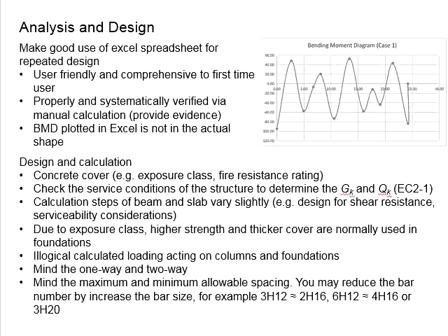And also you need to beware of illogical calculations of the loading acting on the columns and foundations. Sometimes, because you did not actually do proper verifications of the calculations, the result may seem quite awkward. In fact, there are some quick ways for you to cross-check, to have a basic idea whether the calculated result is logical or not.